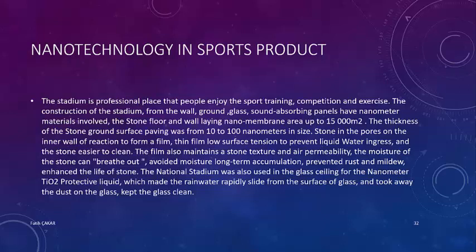The material reacts in the pores on the inner wall of the stone to form a film. The thin film has low surface tension to prevent liquid water ingress and makes the stone easier to clean. The film also maintains the stone texture and air permeability. The moisture of the stone can breathe out, avoiding long-term moisture accumulation, preventing rust and mildew, and enhancing the life of the stone.